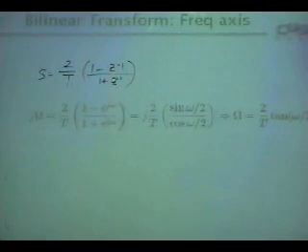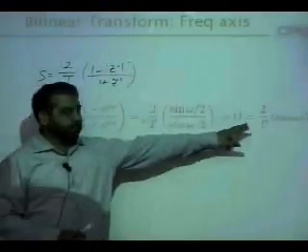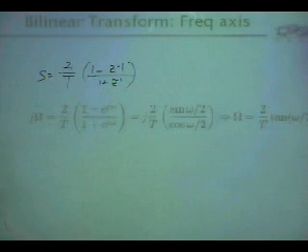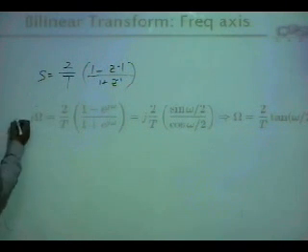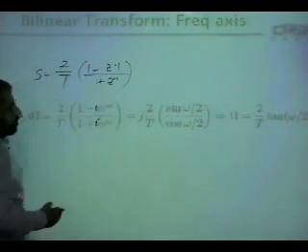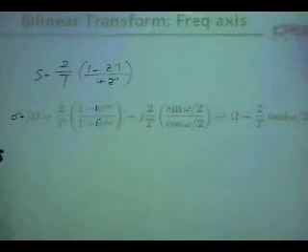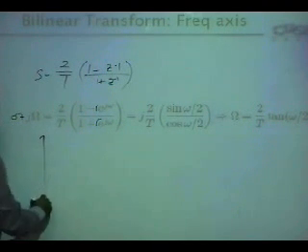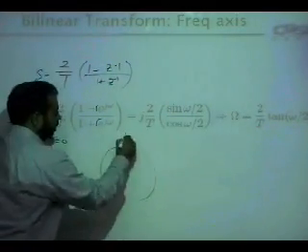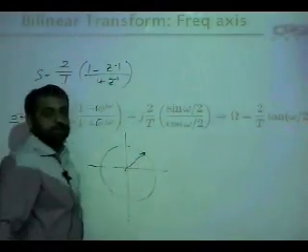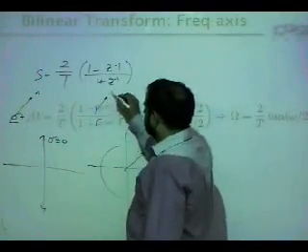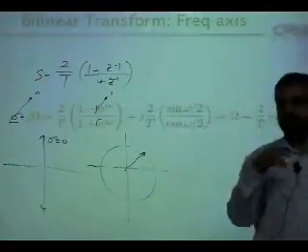Okay, now just to demonstrate that this in fact is the same transformation with which we started. We said we need a non-linear transformation. Simple: you replace s by sigma plus j omega and z inverse by r exponential j omega. We'll also conclude that if you put sigma equal to 0, it means on the z domain you are on the unit circle. We'll shortly prove this. If I put sigma 0, it means r is equal to 1, because the j omega axis is the unit circle.